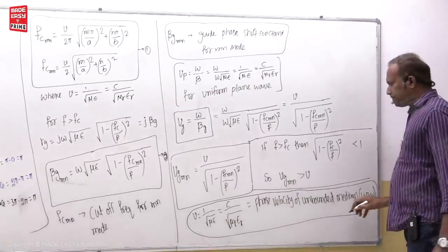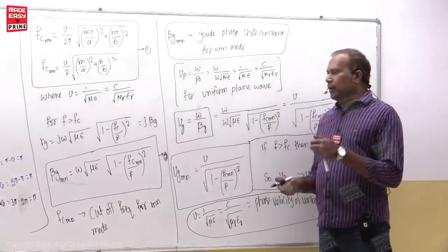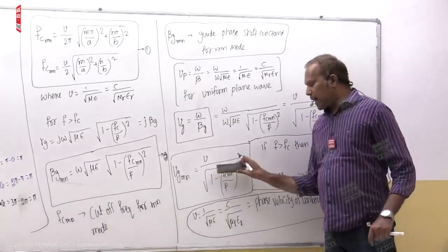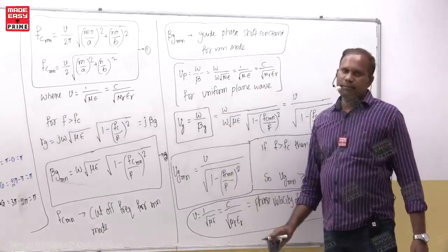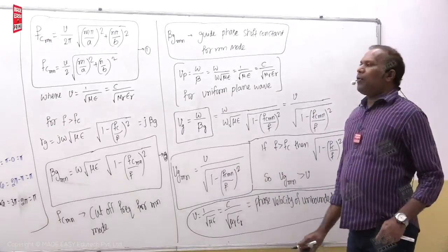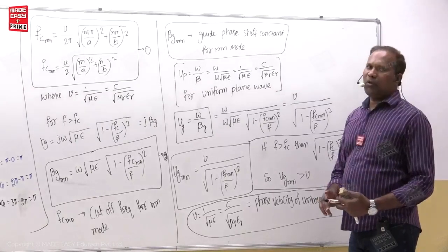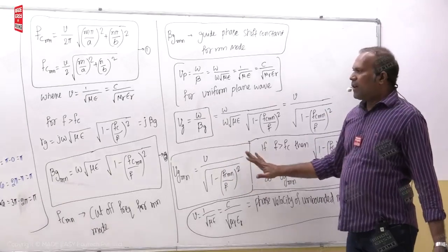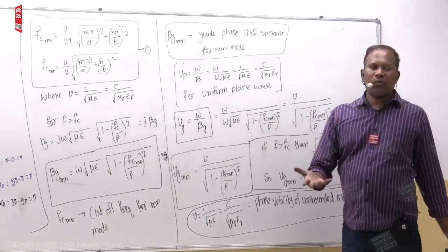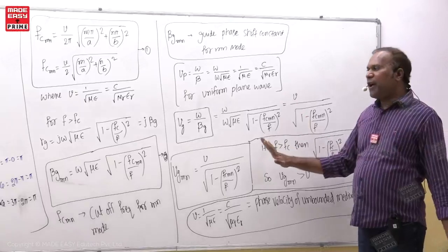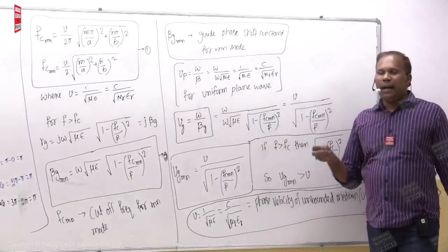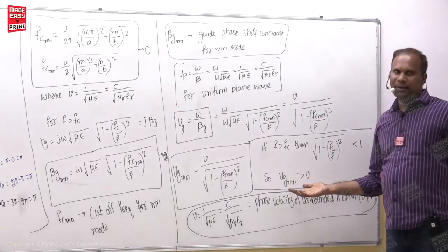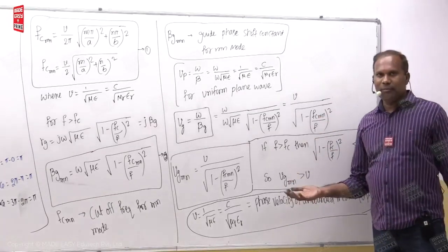So in this formula, I told you, in the velocity formula, beta comes in the denominator. In the waveguide, this factor will be in the denominator for the velocity. So till now, how many formulas have you remembered? Only one more formula is remaining. FC formula, beta formula, then velocity formula, wavelength formula, and the last formula is the impedance formula. Only 5 formulas are required, and it is very easy because for TM modes also the formulas are the same. It is a bonus for you.